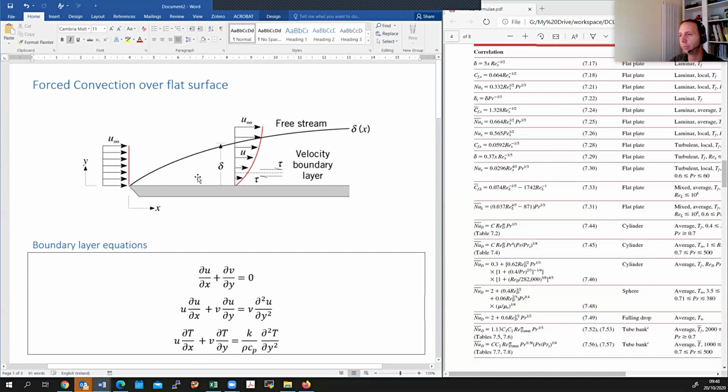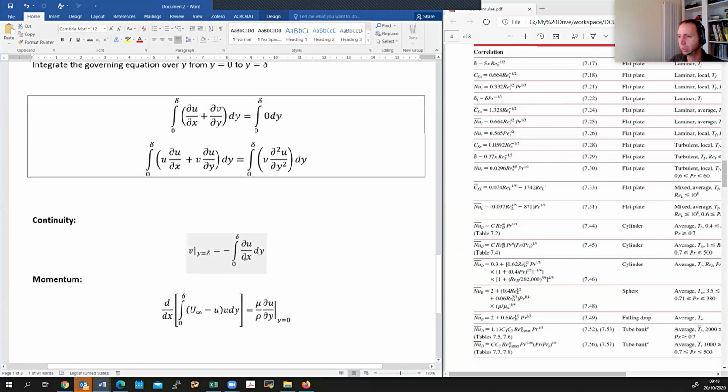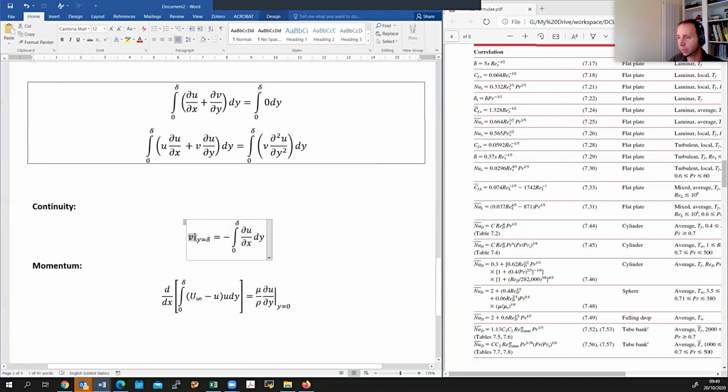You've got a certain amount of fluid inside the boundary layer, and that's what that continuity equation states. So the amount that flows through here is not the exact same amount, I shouldn't say that. It's what flows through a control volume. For example, if you take a control volume which goes from there down that line, and you go down and go back up and follow the contour of the control volume, you've got a certain amount of fluid going in there, a certain amount of fluid going in there, and a certain amount going through the upper boundary. And that certain amount going through the upper boundary is v. It's that y component of the velocity.